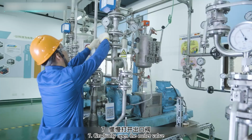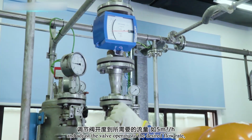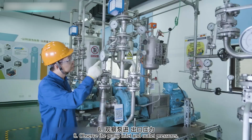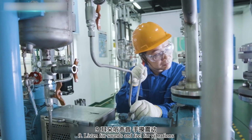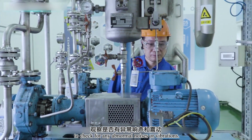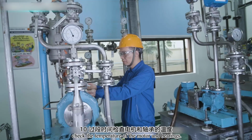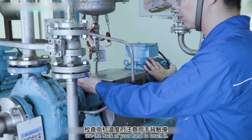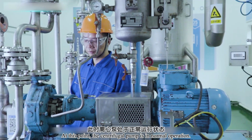Seventh, gradually open the outlet valve and adjust the valve opening to the desired flow rate, such as 5 cubic meters per hour. Eighth, observe the pump inlet and outlet pressures. Ninth, listen for sounds and feel for vibrations to check for any abnormal noises or vibrations. 10th, after some time, check the temperature of the motor and bearings. When checking the motor temperature, use the back of your hand to touch it. At this point, the centrifugal pump is in normal operation.